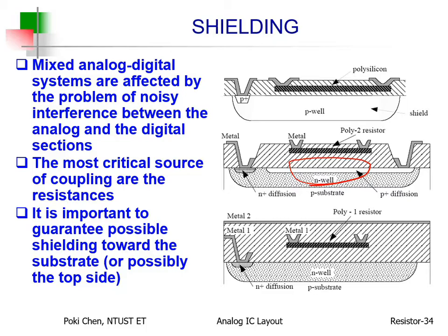No. Okay? If this is poly1, I mean you lower it to become poly1, then it will fully cover the channel area. Here will become the channel area. There will become source and drain areas. Okay? So it means, sorry for that, you won't have this area diffused to be P plus. No, sorry for that. Totally impossible. Okay? If you would like to have the whole area become P plus doping, you need to use poly2.